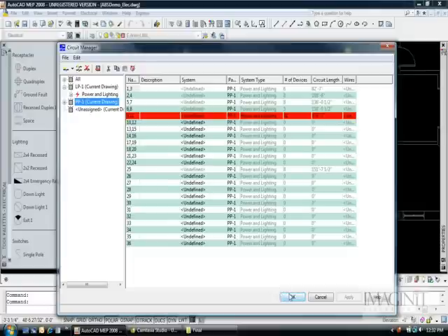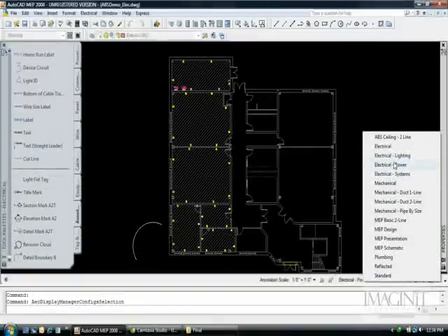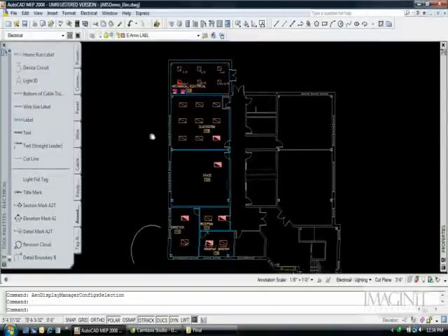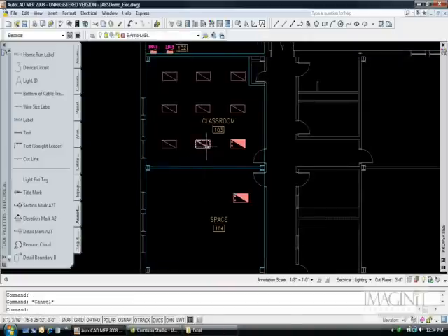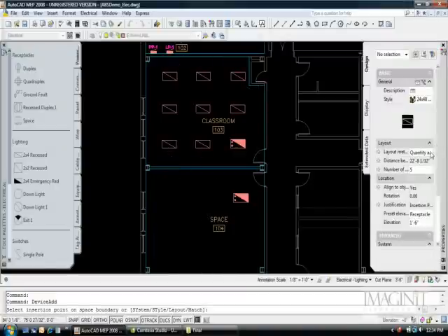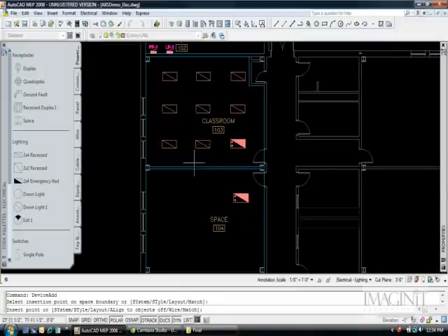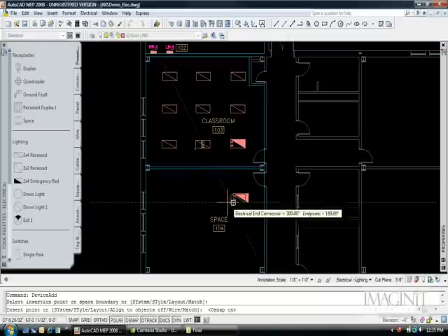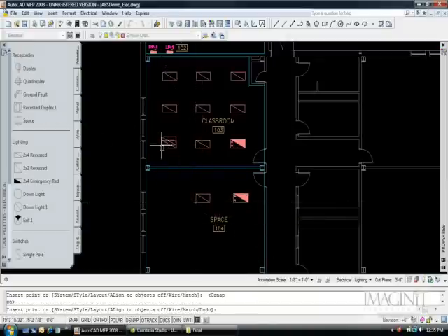Use the tools within AutoCAD MEP Electrical to set up my lighting plans. Now that I have created this particular object, I can go to my lighting tool and create these objects one at a time in this space. And as I use the tools, I can use similar AutoCAD functions such as my O-tracking to help keep objects nice and aligned,